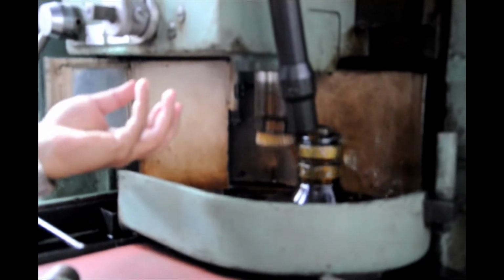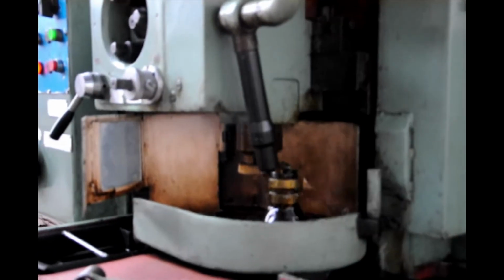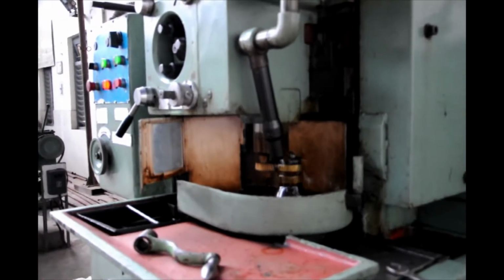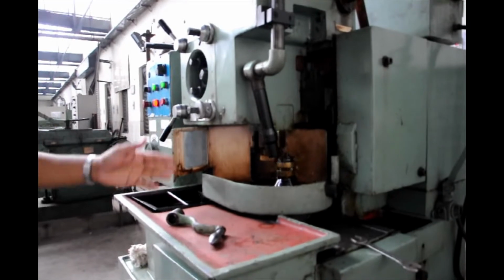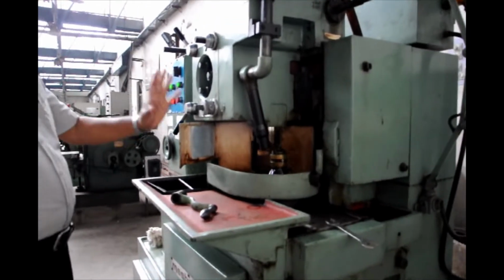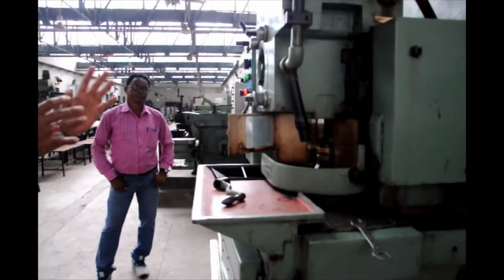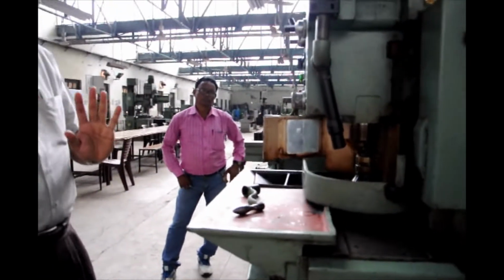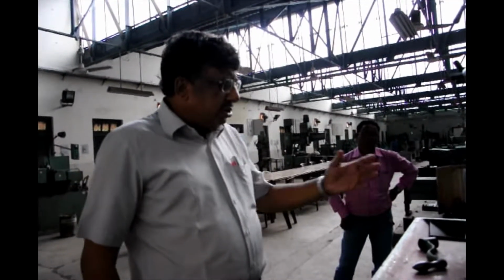And sometimes a little bit of rotation of the cutter is also given so that the wear and other things are distributed, so that the wear is not confined to the similar positions of all those cutters itself. It is a tungsten carbide cutter and is a typical production machine, very rarely available in academic institutions, in tandem with a gear hobbing machine, which can be producing all those parts.